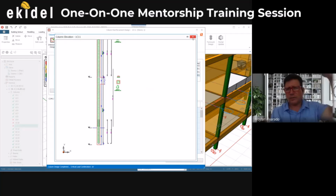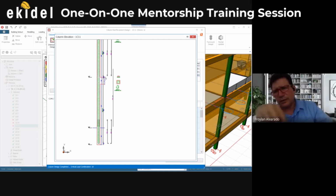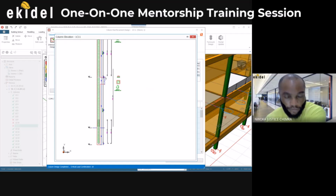Yes. Because remember that if you go with 10, 15, 20-story buildings, you'll have to splice it and you don't want to splice all of them at the same level, no? Because then you'd end up with a weak level. Yes. So you'd have to alternate, no? Yes. Yes, you can do that.